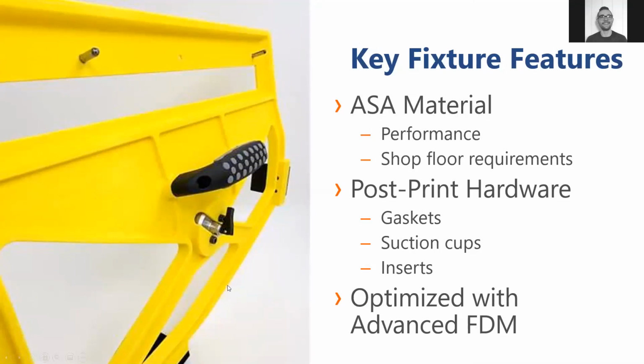So when we went to print this, any hole where we had these inserts put in, we automatically resized it using the hardware insert tool. We also made some of the holes that we couldn't use that tool for self-supporting so that they could be quickly drilled out post-print and the hardware installed, but so that we're not wasting time on the printer by printing support structures. Most notably, these pegs up on the top, they would have had support generated for the duration of the build. So by switching these to self-supporting, we saved a lot of time.